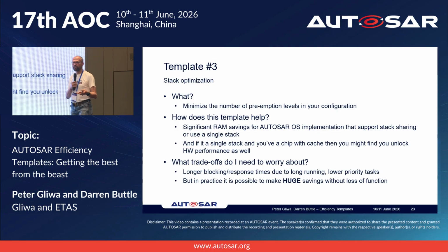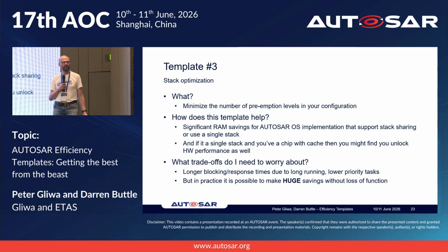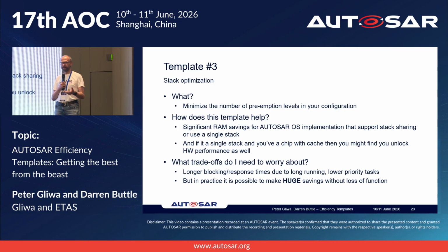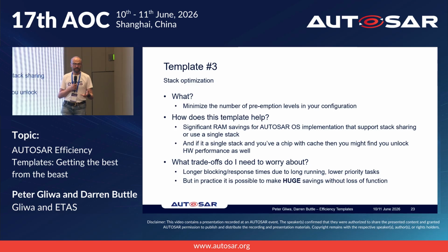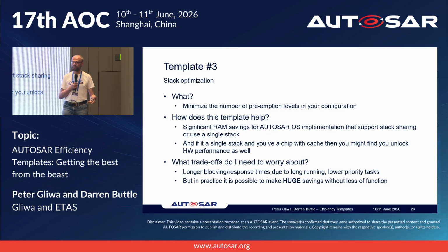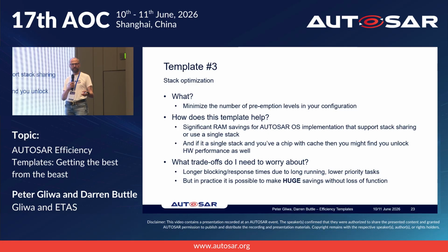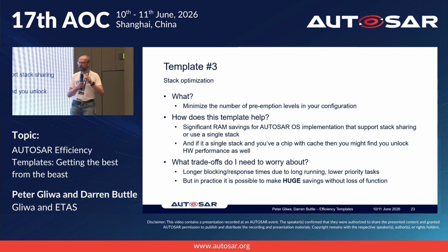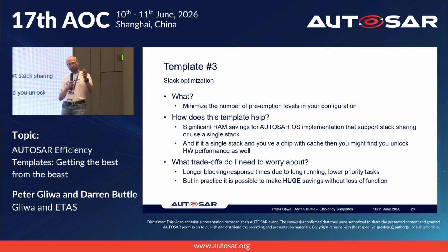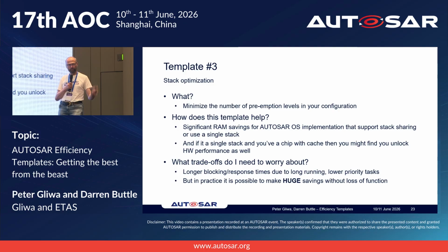Why do I want to do that? Well, what are the most limited resources you've got in your system are RAM, flash, and time. Those are the only 3 variables you've got to play with, and they're all bounded in your ECU. Typically, RAM is the most precious one, followed by time, followed by flash. But obviously, for a particular project, the most precious thing is whatever you've just run out of. But it allows you to start playing around with, okay, where am I going to move some of that load to? Am I going to move it from the space domain into the time domain or vice versa?